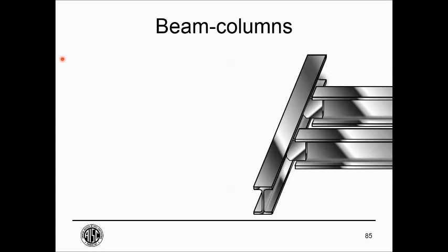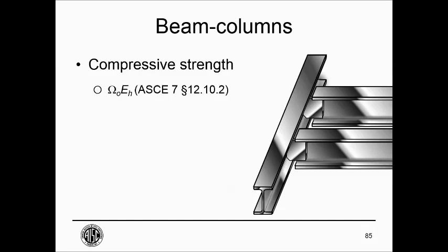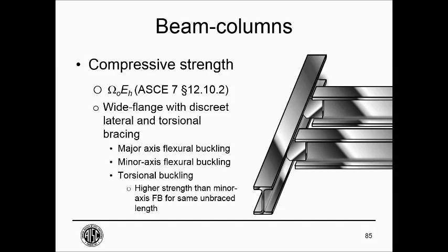Collectors are members that are required to resist axial force, and because they're part of the floor system, they also resist flexural forces. The compressive strength, well, we're designing them for the omega sub O loads. Typically, these are wide flange members with discrete bracing of the bottom flange.